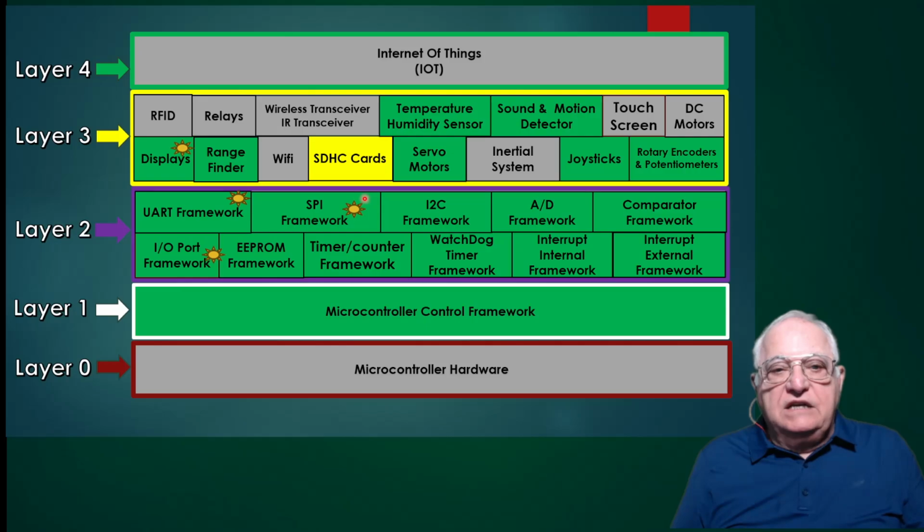So the SDHC, as I noted before, is part of our layer 3, and we're going to be using from layer 2 the UART framework, SPI framework, IO port framework, and also from layer 3 we're going to use the display capability.